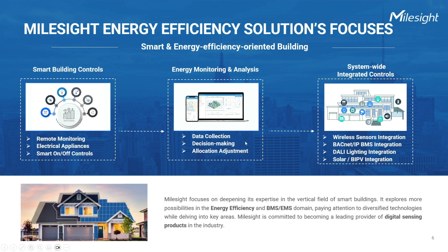Finally, we want to help you integrate different technologies organically to achieve system-wide integrated control. This allows coordination between subsystems, forming a comprehensive building energy management system to improve energy utilization efficiency and reduce energy waste. Examples include LoRaWAN sensors integration, building management system integration through the BACnet/IP protocol, DALI lighting system integration, and building integrated photovoltaic connection.